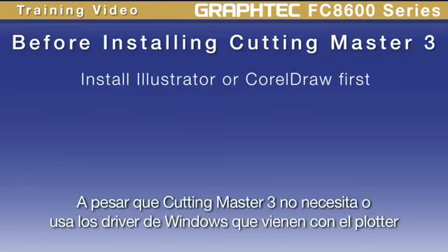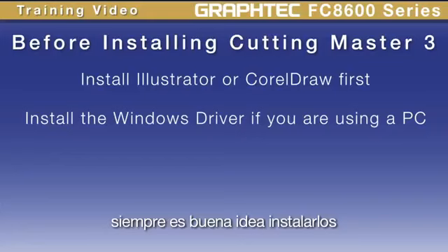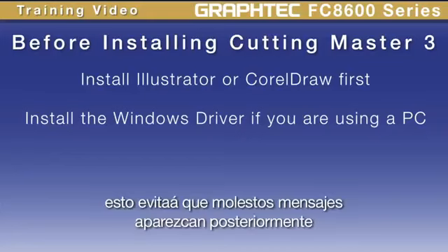While Cutting Master 3 doesn't need or use the Windows drivers that came with your cutter, it is always a good idea to install the drivers. This eliminates annoying plug-and-play messages appearing later on.